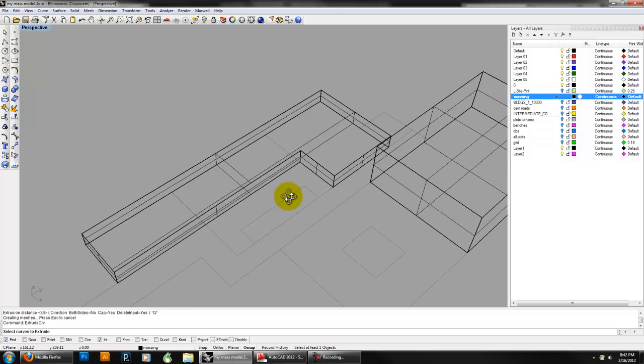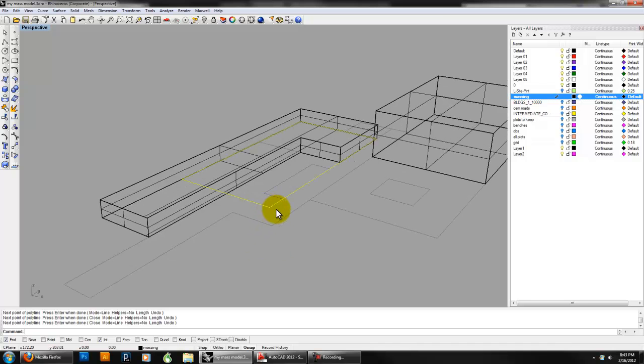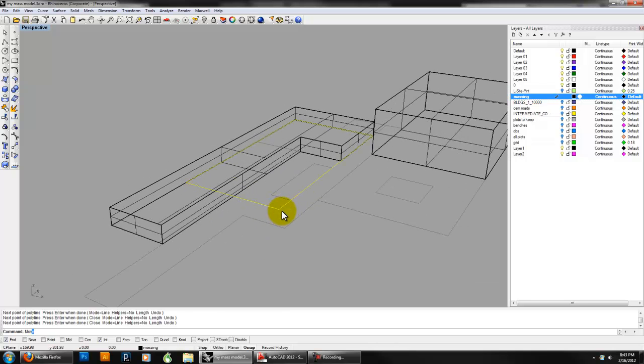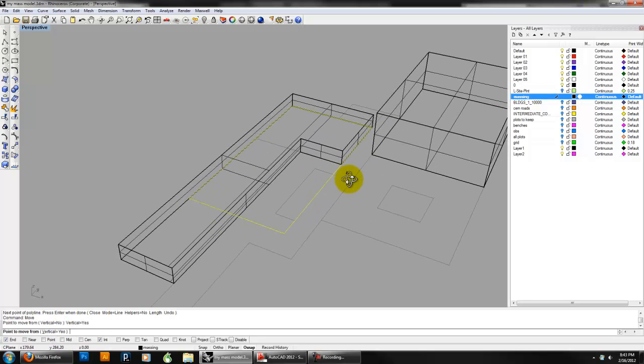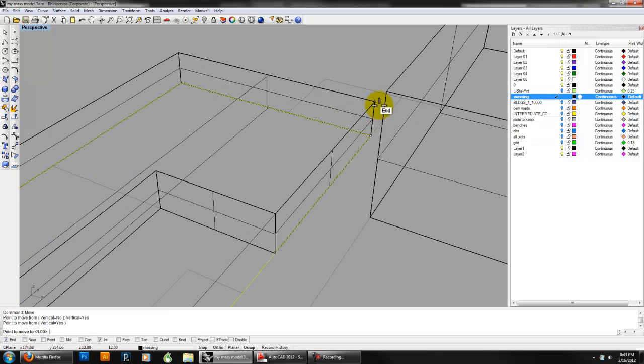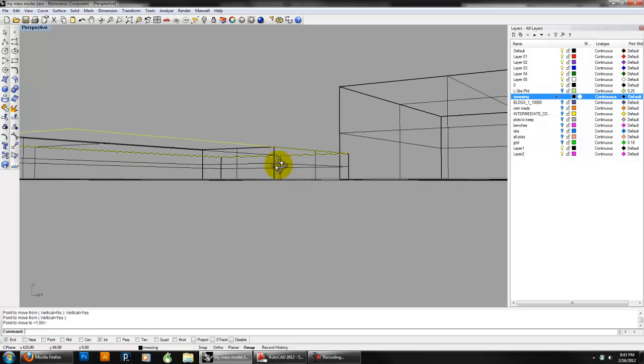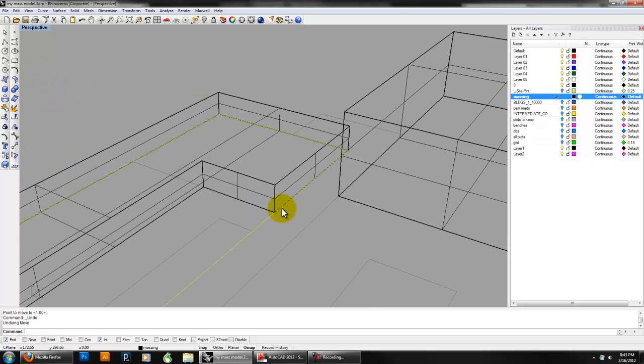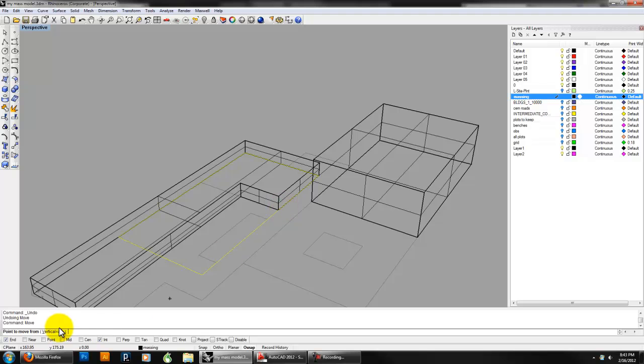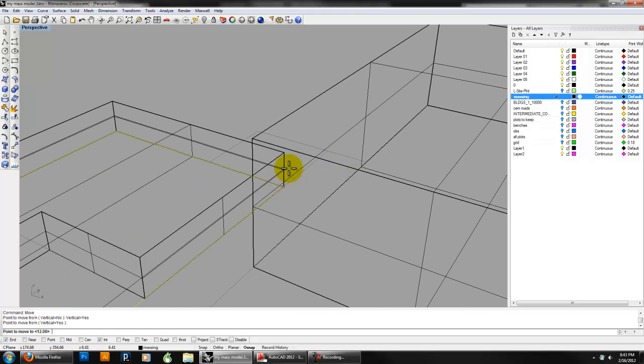And my second story is going to be, let's take my polyline here. I'm going to snap the base here. Okay, I've got this piece, and that's actually the second story, so I'm going to move vertical, yes, and I'm going to move it from 0Z to the top of that, so now it's at a height of 12 foot. Again, move it, click vertical, yes, and click it, and move it out.